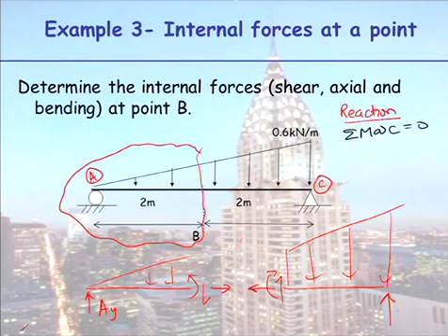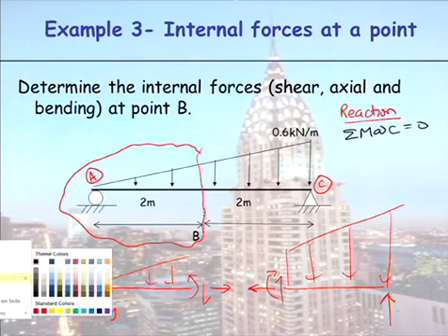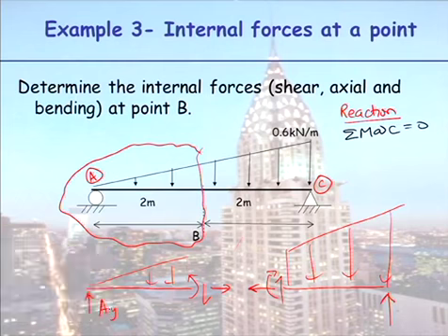So taking moments at C, the first thing we need to do now is come up with our resultant, or our equivalent point load here, as a result of that triangular load. And I have drawn it off centre, because for a triangular load, the resultant force we know occurs a third from the high end or 2/3 from the zero end. So I've marked that distance in there now, 4 on 3.